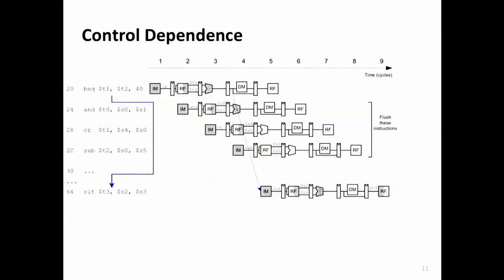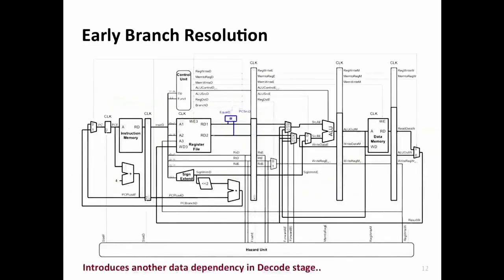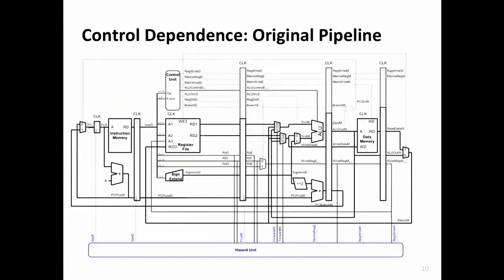If you look at this, this is source register 1, source register 2, you need to check the equality of those. Basically we add specialized logic that checks the equality of those source register values, and if they're equal, then we add special logic that selects the target address from this target address computation logic, right? So this is where we computed the target address. We kind of moved that over here also, right?